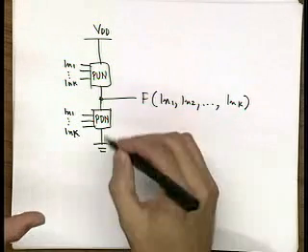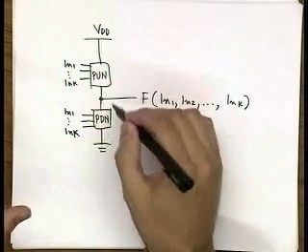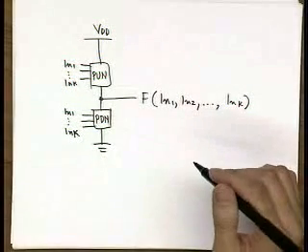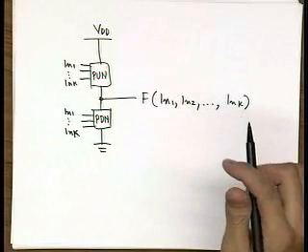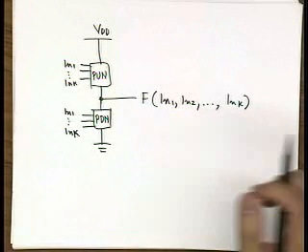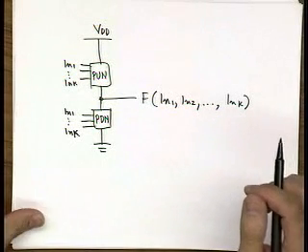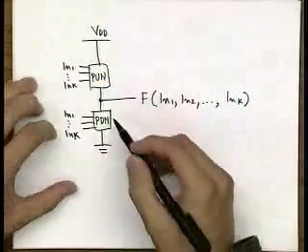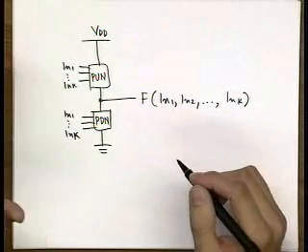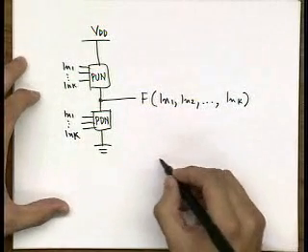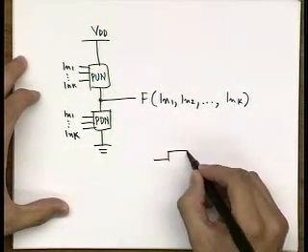So now let's see how we can realize these pull-up and pull-down networks in practice using transistors, and see what kind of logic operations we can perform using various configurations of transistors. In order to realize a pull-up and pull-down network, let's first review some of the basic switching properties of MOS transistors. We have two types of transistors we can use.